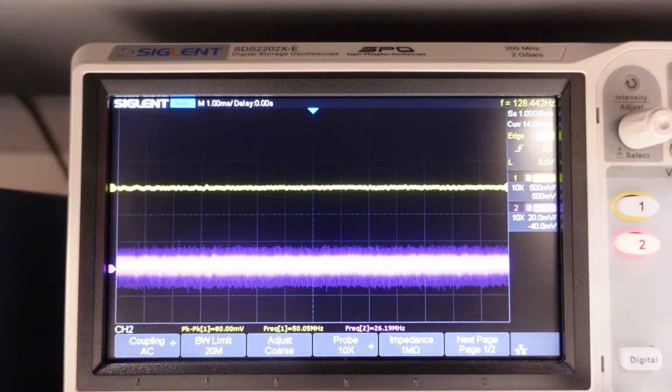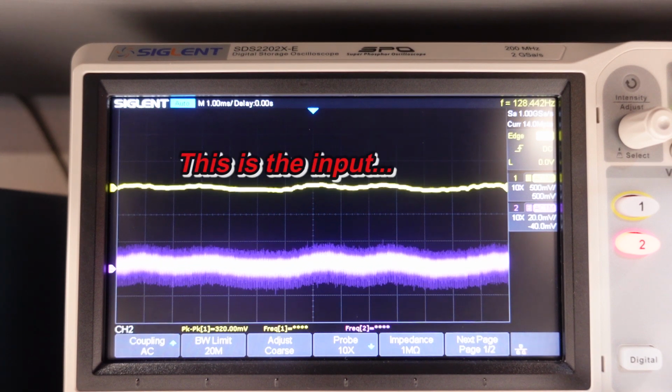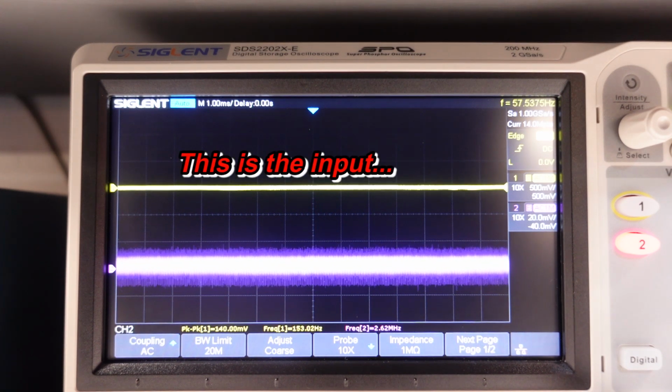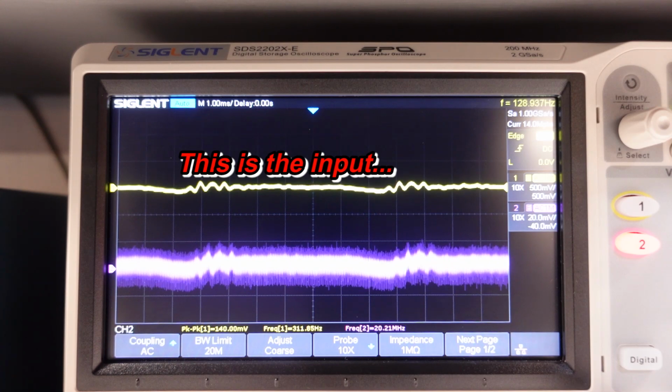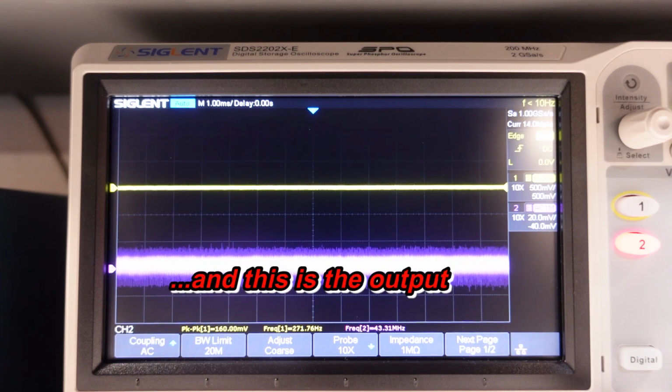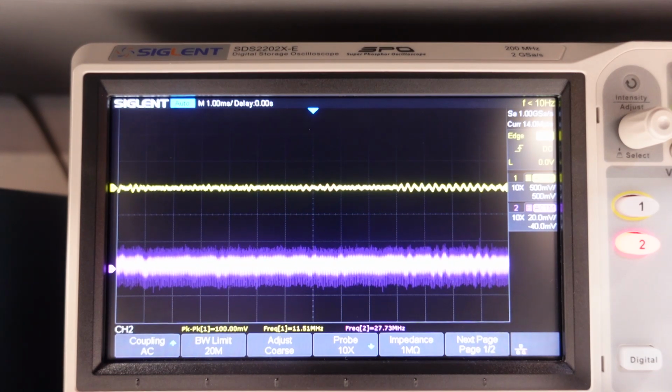As a final demo, I've taken one of the voiceover tracks from my prior episode and played it to the input. The final element that I need in this section is a low-pass filter. The bandwidth of the MAX9814 is 20 kHz, which is much more than I need. For basic voice communication, around 3 to 4 kHz is plenty.